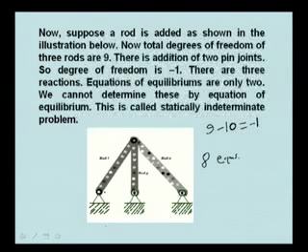You have to find the x component and y component of the reaction. So 2 here, 2 here, 2 to 4, 2, 6, and plus these 3. So you have to find 9 components, but you have got only 8 equations. Naturally this cannot be solved by statics. Therefore this problem is called a statically indeterminate problem.